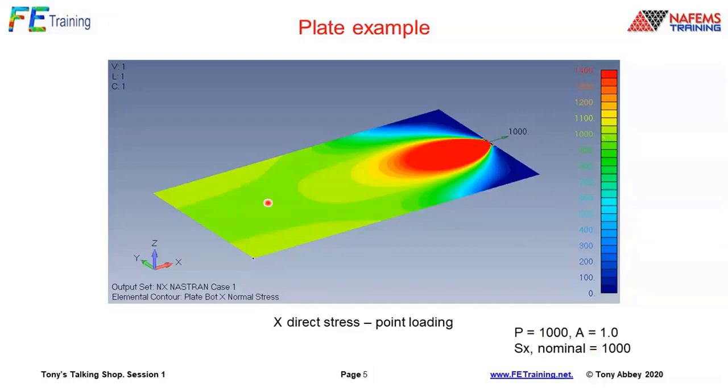So this was our target region. We can see we've got diffusion back to the nominal stress at that point. Again, it's a bad idea to apply a point load, so this is something we wouldn't typically want to do in an analysis, but just really to show the point. And just to emphasize, this is a stress singularity. The stresses go off to very, very high levels here, which we'll show shortly.